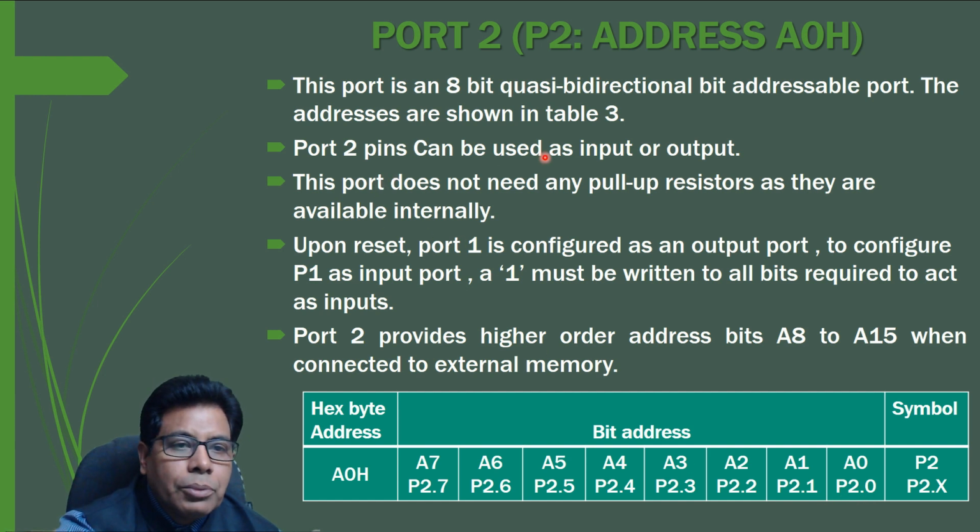Then it can be used as an input or output, and again it does not need any pull-up resistors as they are available internally. Upon reset it is configured as an output port, and when we want to configure it as an input port, one must be written to all the bits required to act as inputs. Then it has an alternate function. It provides higher order address bits, that is A8 to A15, when connected to external memory.